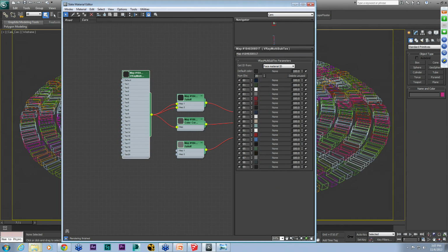I'm wondering if he's saying if there was a map underneath all the cars, with grayscales, right? Like each grayscale, we change the... I think what they're asking is if they had a map with grayscales, and he could use the grayscale as an intensity, where the black would be like the red cars. You would only have 2 or 3 options though. There couldn't be that many options if that was the case. That would have to be done through scripting, I believe, to check the bitmap's color and then assign the material ID to the object. It's sort of how ForestPack works, in a broad sense, but I don't know how you pipe that into the geometry, if that is indeed the question.